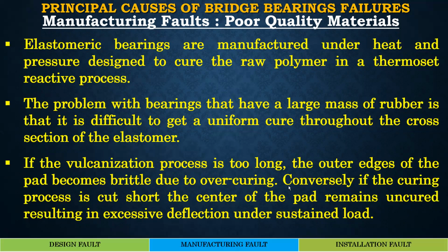The problem with elastomer bearing manufacture is that they have a large mass of rubber, and it is difficult to get a uniform cure throughout the cross section of the elastomer. Vulcanization process has to be very, very controlled. If it is too long, the outer edges of the pad become brittle due to overcuring. Conversely, if the curing process is cut short, the center of the pad remains uncured, resulting in excessive deflection under sustained load.